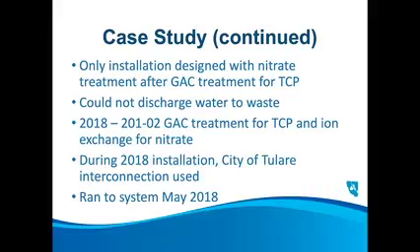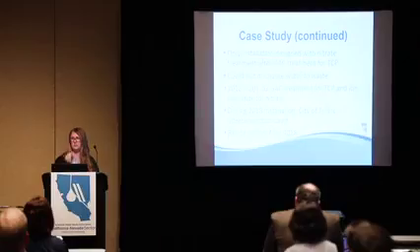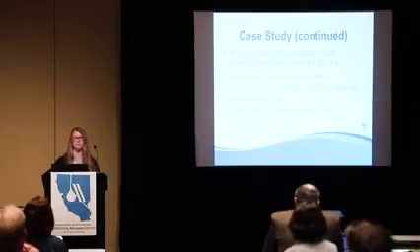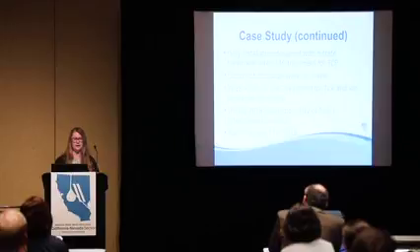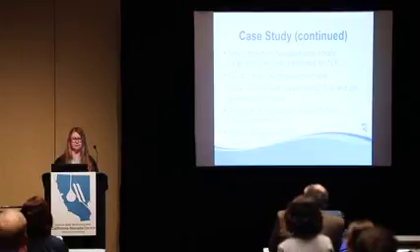The other challenge we had at this site is that it was very difficult to discharge water to waste. When we're starting up the treatment, there are a number of different flushings that have to occur with the disinfection of the vessels that are installed, and then just with getting the GAC loaded in and that type of thing. So there were some challenges with that, just some things to think about. Then we eventually got the GAC installed for the TCP treatment, and a small, at that time temporary, nitrate treatment system using ion exchange.